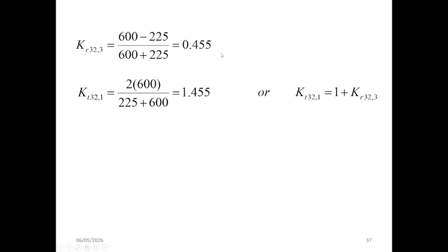This positive value indicates that a portion of the incident wave is reflected back without polarity reversal due to the impedance increasing from 225 ohm to 600 ohm.